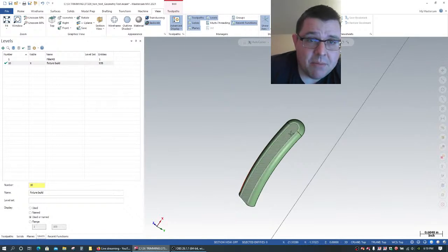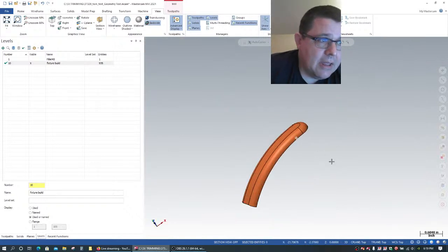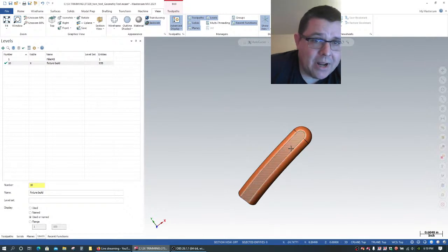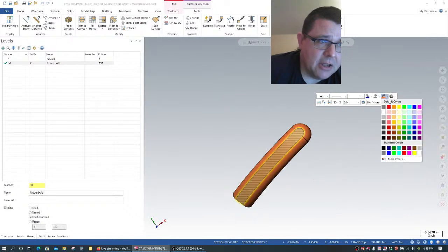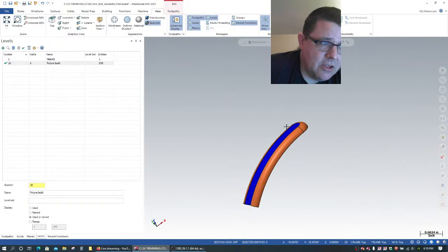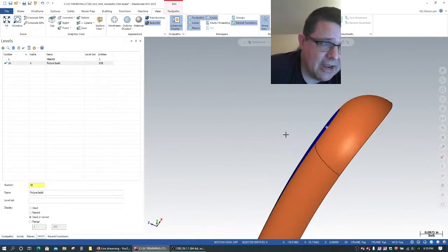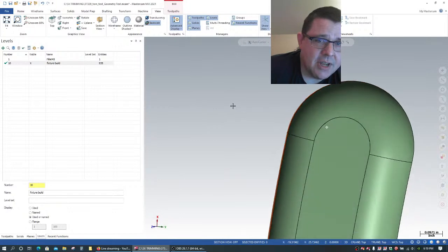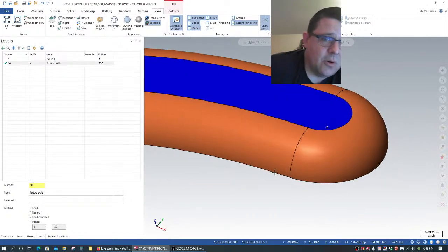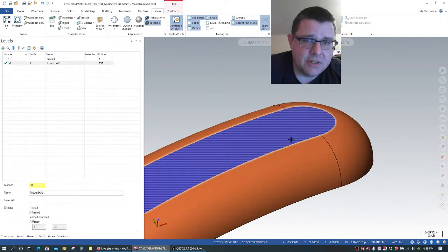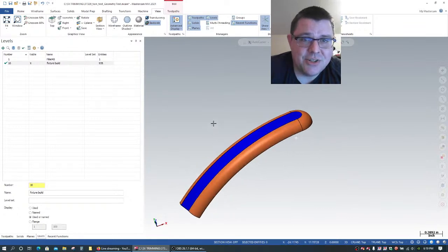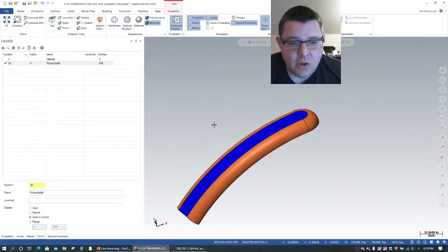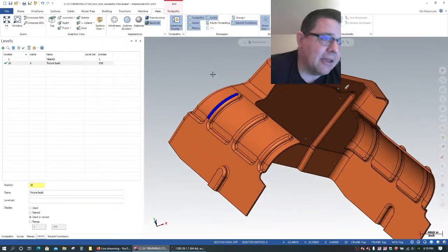And I'm doing that to show you the back side of the surface. So with backside turned on, the front side of the surface is whatever color the surface is. If I change this color to, say, blue, you can see the surface is blue. It looks good. If I look at the backside, it's all this kind of olive color. And so when it's a surface, not a solid or solid face, you can actually see where the backside of the model is. So I'll do Alt-E to bring everything back.